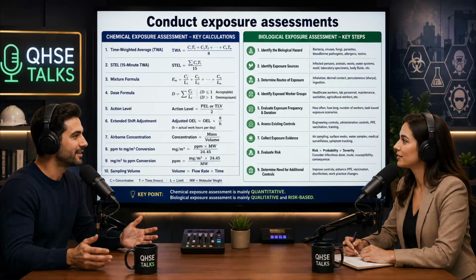Okay. Finally, we divide that sum by the total time of the exposure we measured. So 1 hour plus 2 hours plus 0.25 hours is 3.25 total hours. So 1,287.5 divided by 3.25 hours. Which yields a time-weighted average of 396 ppm. So for that specific 3.25 hour block of their day, their average exposure was 396 ppm, despite hitting that massive 750 ppm peak.